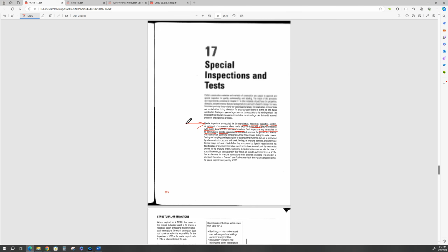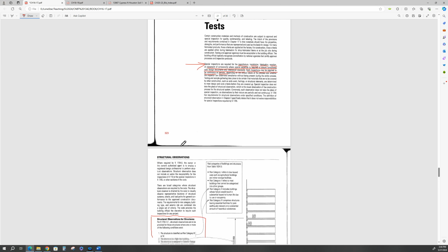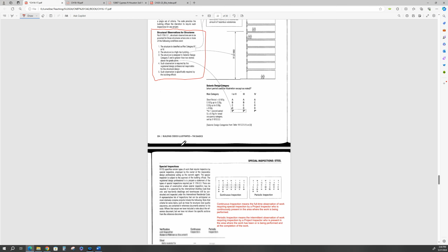Now, under manufacturer, let's go back up under here. Under manufacturer, you may have to send an inspector. I, as an engineer, have gone to a manufacturer's plant and observed the testing of pumps and mixers and gearboxes and such as that. Then we've had inspection on the installation, fabrication under structural steel or pressure vessels. Then we've had inspections for the erection and placement of special components like HVAC and plumbing, etc., etc., etc. Okay? All right.